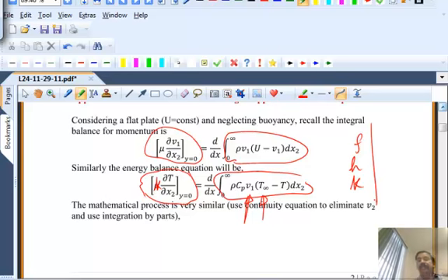Okay, and in the case of the molecular process, it's mu, it's the thermal conductivity, I guess I should call it Kg, and this is the diffusivity. So this is the similarity in the constitutive equation for molecular processes. Momentum transfer is governed by viscosity, heat transfer by thermal conductivity, mass transfer by diffusivity. But the macroscopic quantity that we are interested in computing is the friction factor for fluid mechanics, heat transfer coefficient for heat transfer, and the mass transfer coefficient here.